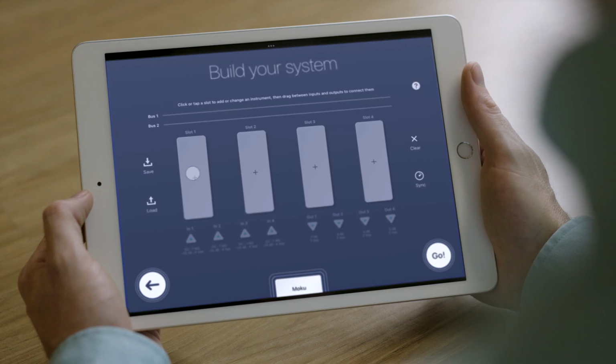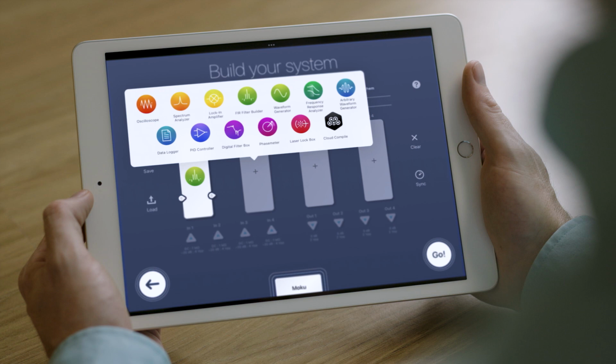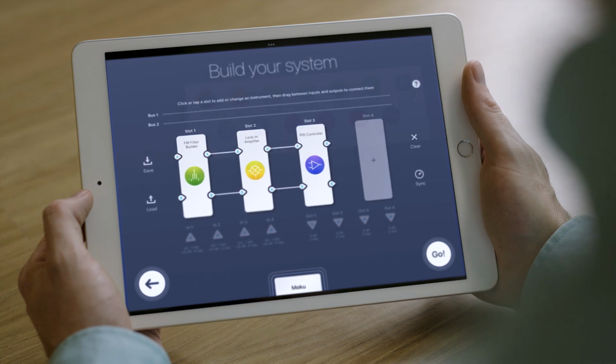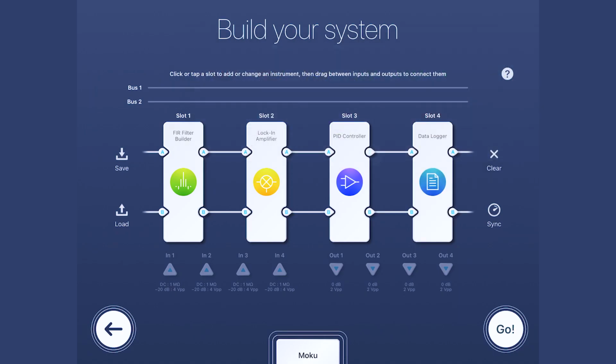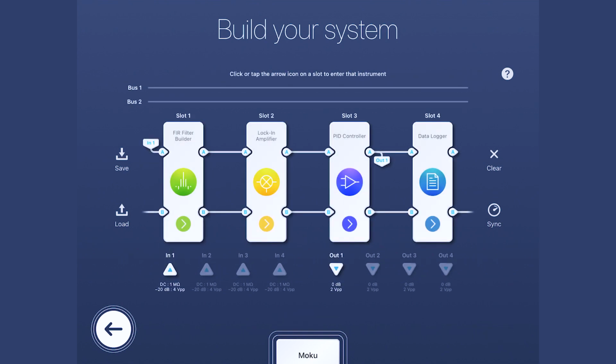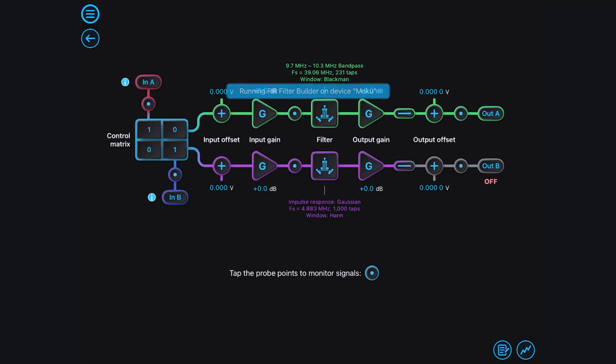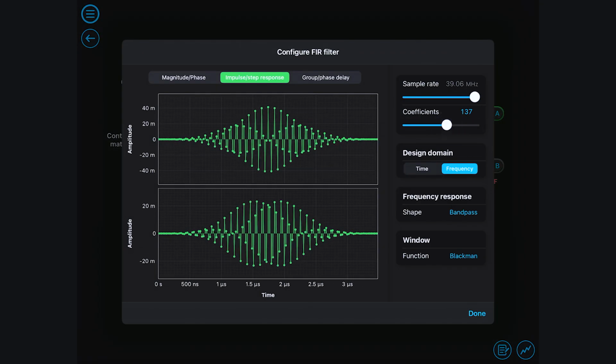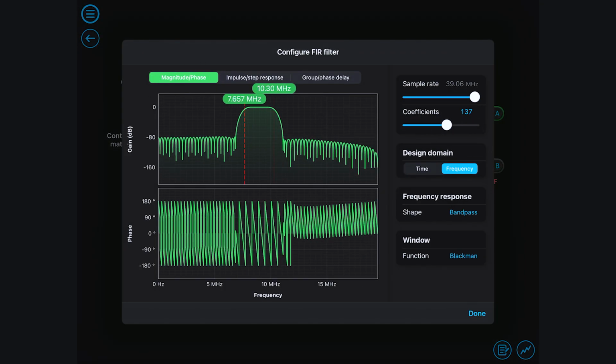Moreover, since Moku Pro gives you the ability to use more than 12 embedded instruments, the PID controller is more tightly integrated with other capabilities, like lock-in amplifiers and filter boxes, data loggers, and more. Record your inputs and their responses, you can apply pre- and post-filters, and get real insight into your system from a single device. The software-defined instruments reside on powerful hardware to enable advanced testing.